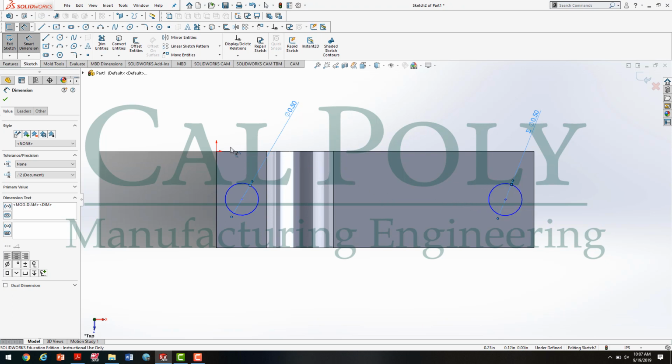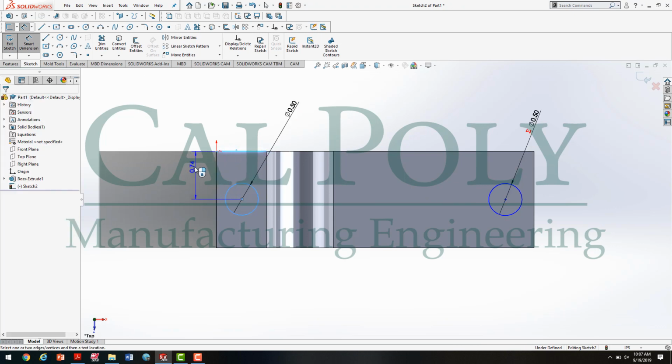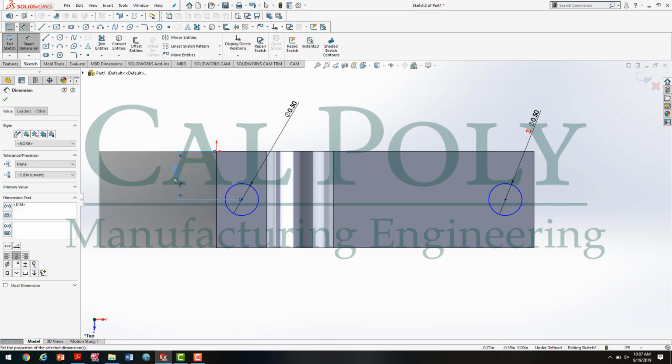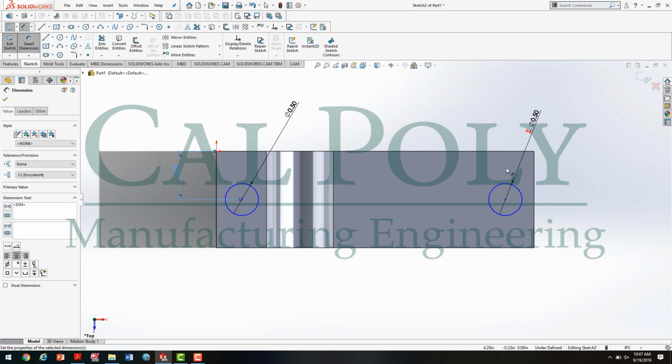I'm going to go ahead and select the location. So I'm going to locate this circle from the top edge and drag the dimension out. At this point, let's say I knew the part was 1.5 overall and it's right in the middle, so I could do math. If I was bad at math and didn't know that it was 0.75, I could do 1.5 divided by 2, tab, and check mark. That'll go ahead and make it 0.75. Double click to show you. Again, let me show you that again.